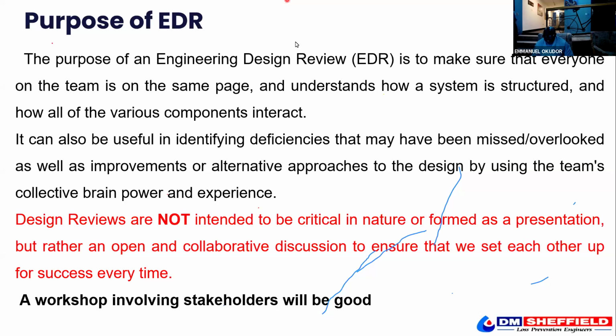So design reviews are not intended to be critical in nature or form a presentation. Yeah, it's not a workshop that people just come, make a presentation, and everybody claps. No, before the presentation, which is the workshop, we must have access to a lot of this document: pages for design, P&ID, cause and effect, simulation report, as the case may be, calculation sheets.